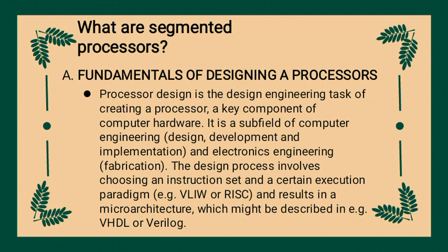Processor design is the design engineering task of creating a processor, a key component of computer hardware. It is a subfield of computer engineering: design, development and implementation, and electronics engineering fabrication. The design process involves choosing an instruction set and a certain execution paradigm, VLIW or RISC, and results in a microarchitecture which might be described in VHDL or Verilog.